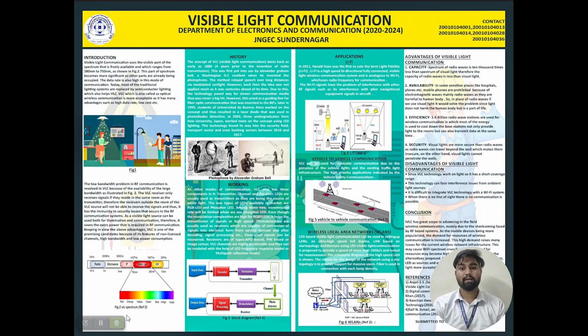Now I shift to longer range. In longer range, we use 4G to 5G communication techniques, which is greater than 1 kilometer. It is the combination of DSRC plus GPS technology. In this, DSRC stands for Dedicated Short Range Communication, which has a frequency of 5 to 5.9 gigahertz. And mainly, V2V communication is used in safety measures like current GPS position, path history, path prediction, and vehicle control information like braking status and steering wheel angle.